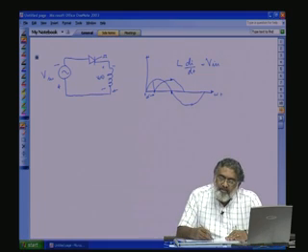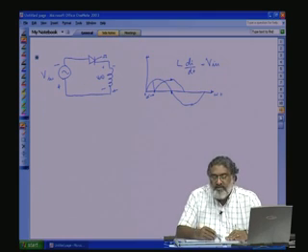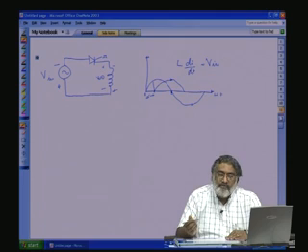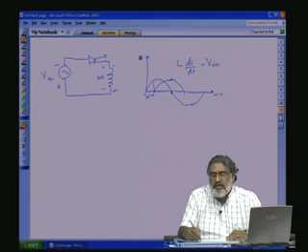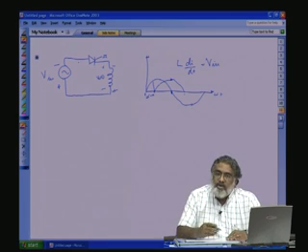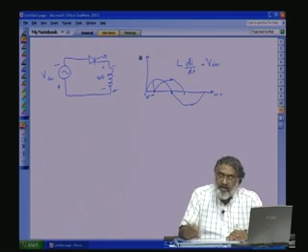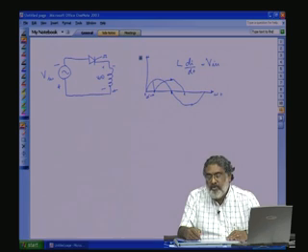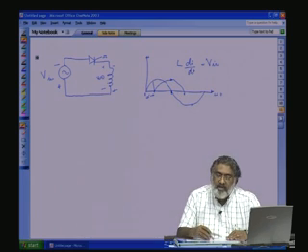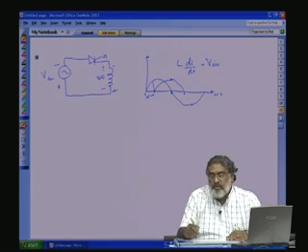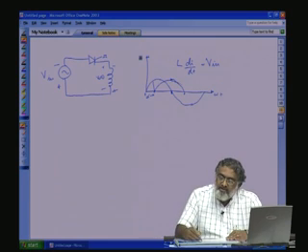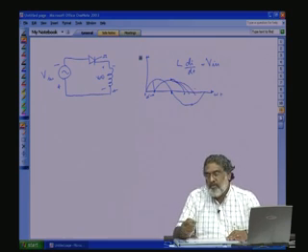Now, this voltage L di by dt minus this voltage will force this thyristor in the forward conduction state, and the thyristor will continue to conduct till the current comes to 0. The moment current comes to 0, the thyristor will switch off, because a thyristor cannot conduct in the opposite direction. So, this point where the conduction comes to 0 is not in our control. It depends on the inductance and the initial load current, the maximum load current flowing through the system. So, with various inductance, sometimes it can extend this way, sometimes it can extend this way also. So what it means, we lose control.